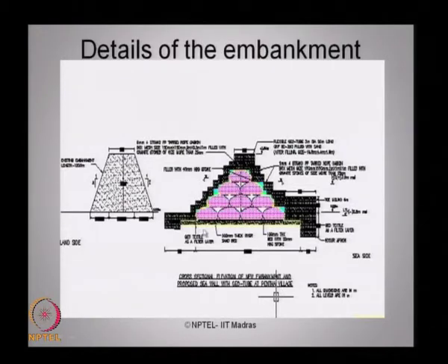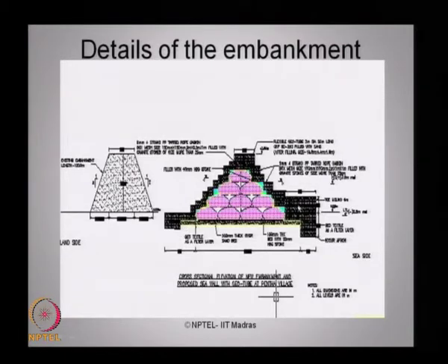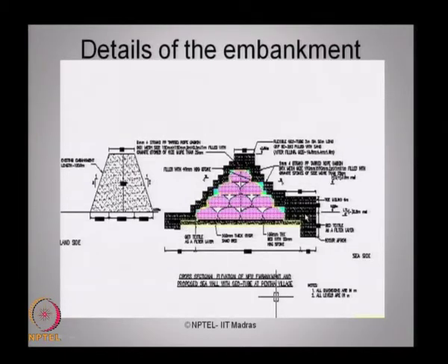Once the geotubes are fixed and laid, over this we provide gabion boxes which are mounted and covered with 200 mm size rubble stones, which can offer enough resistance by counterweight to hold these geotubes in position.